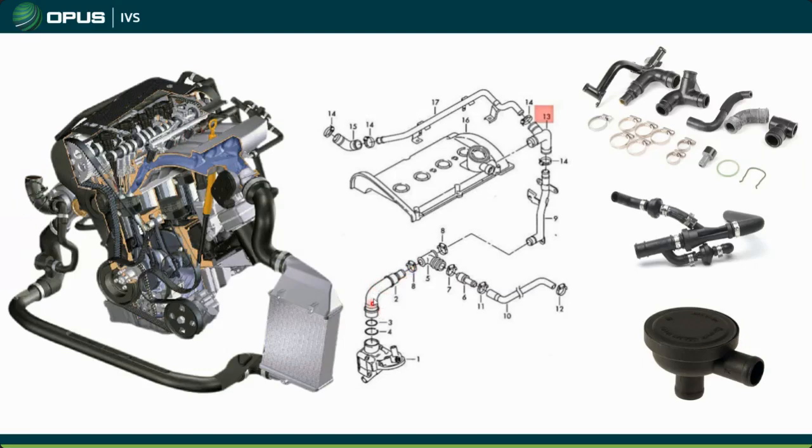These things, they crumble. I mean, they come apart, and more often than not, what'll happen is you'll go to replace these things, and you'll find all of these hoses and tubes and everything are just totally coming apart. You look at them wrong and they crumble. So you'll end up basically replacing all of these components. And that would be my suggestion. If you ever really get into one of these, just do them all, because of course the one that you're not going to do is going to be the next one that comes back leaking, and you're going to have an unhappy customer.